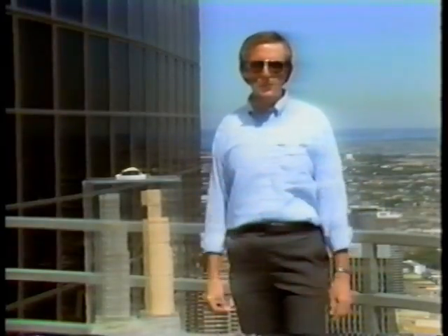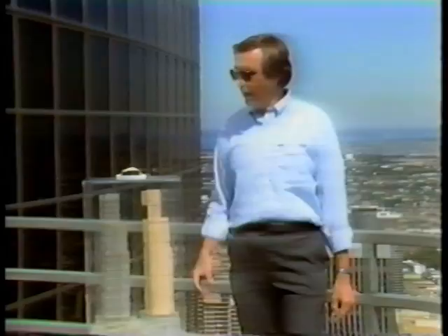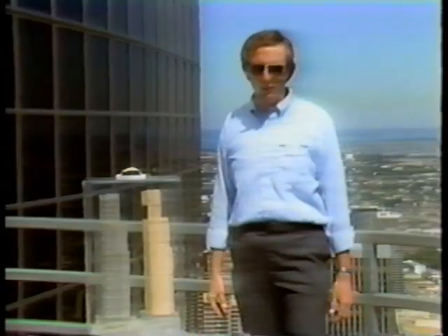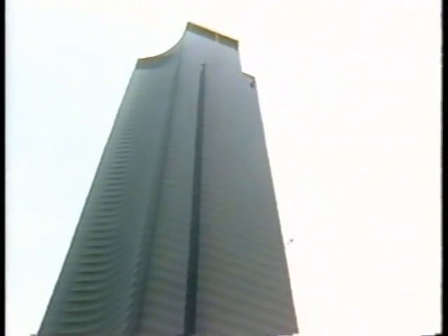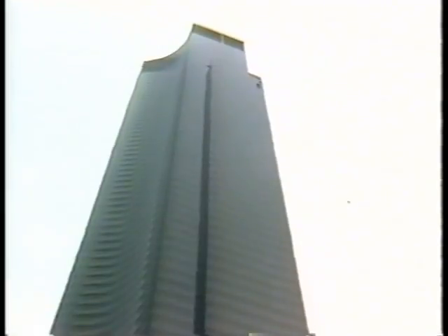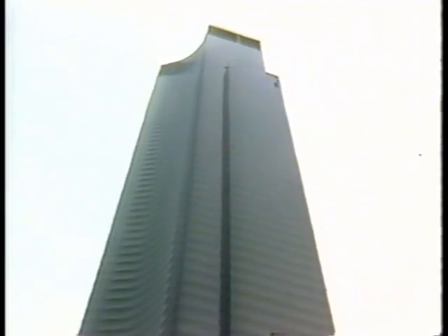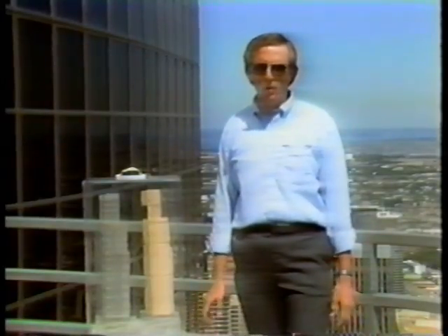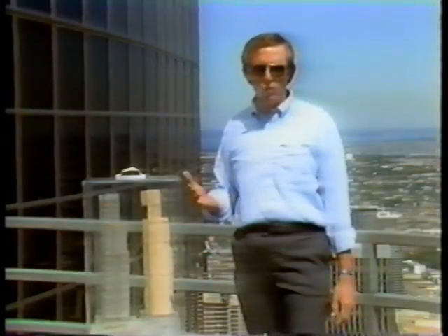The period of vibration of Columbia Center differs slightly in the north-south direction from that in the east-west direction, but they're around 5 seconds. There's also a period of vibration associated with twisting of the building, and that's in the 4-second range. In the maximum storm that the building could ever experience, the motion at the top would be a total of approximately 18 inches. Normal motions under normal winds are very small and cannot be perceived as rocking by the occupants. The period of the building is 5 seconds per cycle, so the frequency is the inverse of that, 1/5 of a cycle per second.